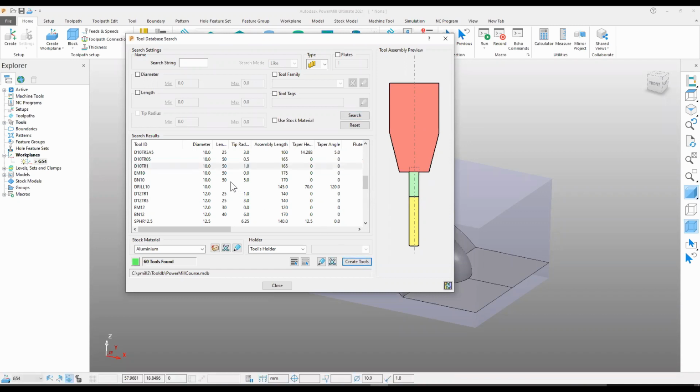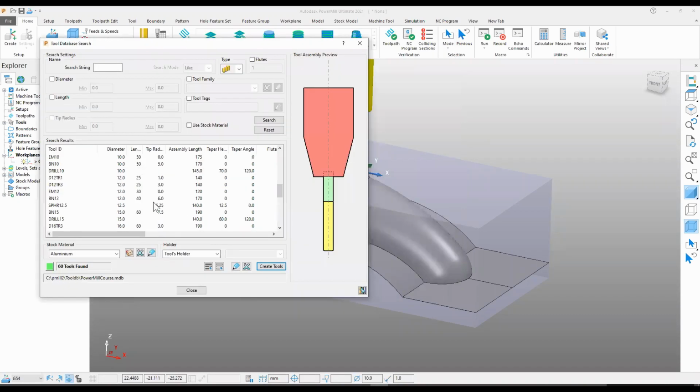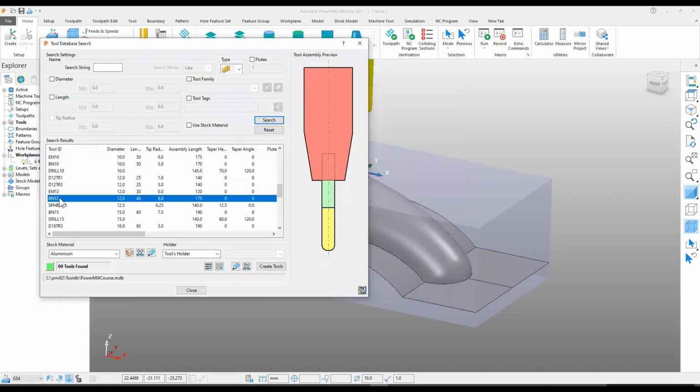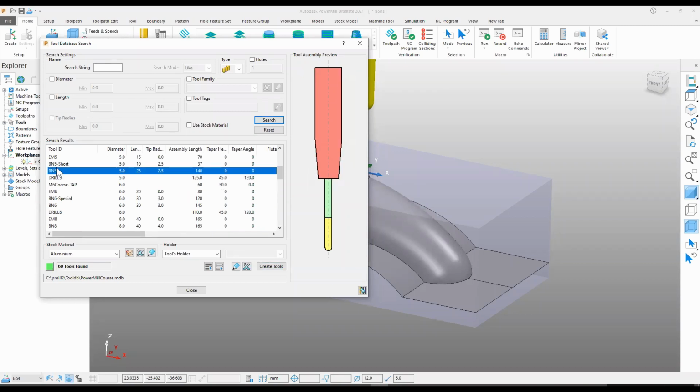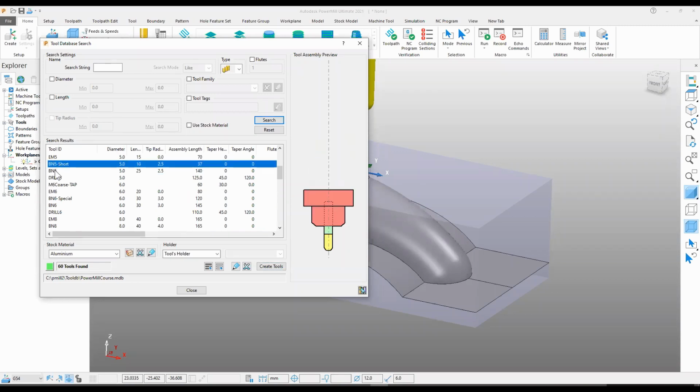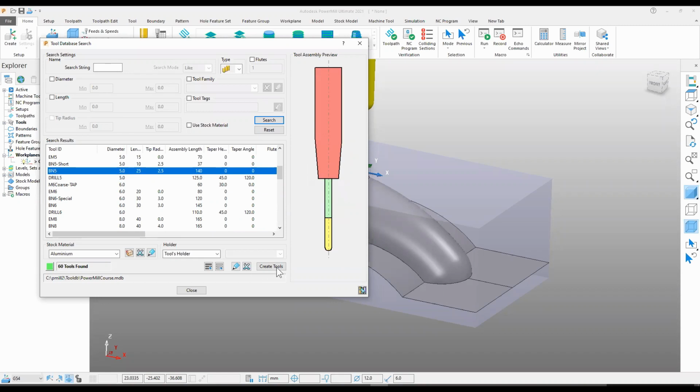And I know that we will have to finish off some of the big surfaces on the part. For this one, I will go for a ball nose tool with 12mm diameter. So I want to create this. And I will know that in the edges, we have then some rest material that I want to finish off. And I go for a 5mm tool. This is a little bit too short, takes a little longer one, and create this one for me.